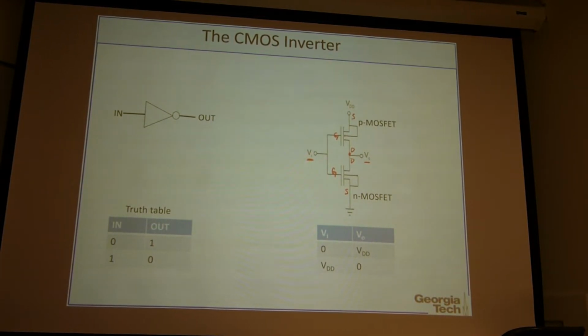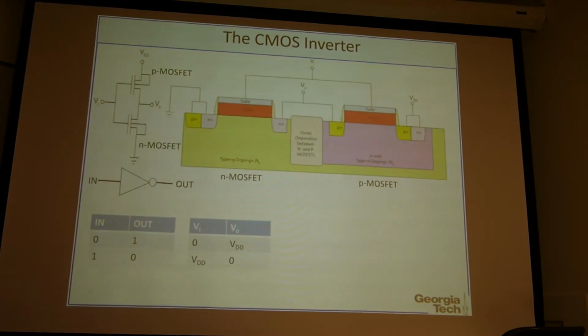Because this is CMOS, you have NMOS and PMOS. Alright, so again, you see this kind of cross section. You have seen this in the previous lecture. The NMOS is built in the P-type substrate, and PMOS will be built in this N well. And you ask about the body contact. Where is that? Okay.